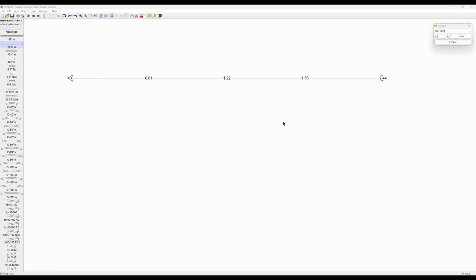Now we want to stack this slope section, and we're going to use a copy paste. We're also going to take a look at the layering to see how this works here. The active layer is layer 0. We're going to change it to 1 here. Now you see that little dot there? That means there's objects on that layer. The rest of these layers have no objects on them. But when we copy and paste it, you'll see layer 1 now has objects on it.